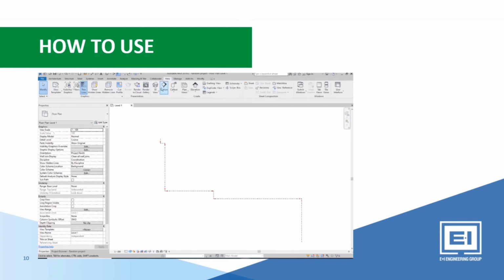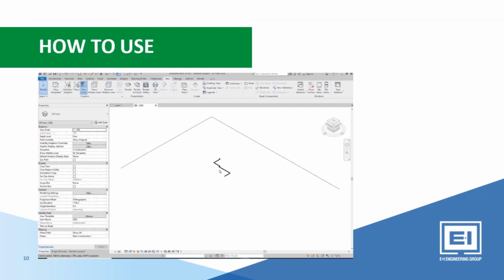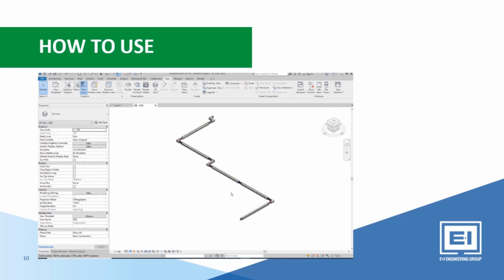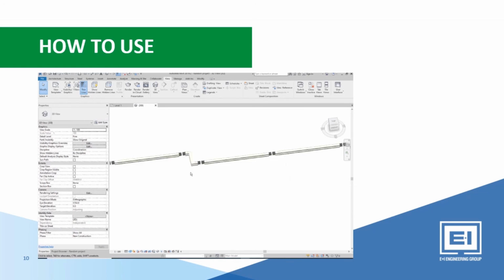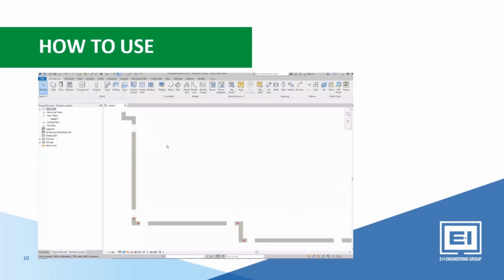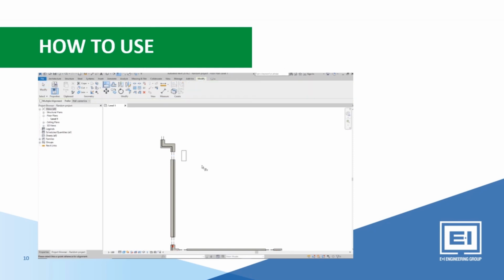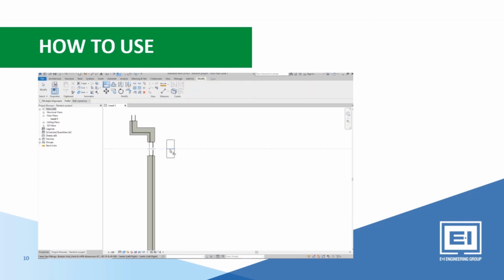Revit also has a 3D view section to enable us to view the model in 3D, as it helps give a more realistic form. Select the View section, choose 3D View, and click on the default 3D. In this view, we are able to move the model with the mouse wheel or at the top left corner, the navigation box, to view the model from different sides, top, bottom, left, and so on.